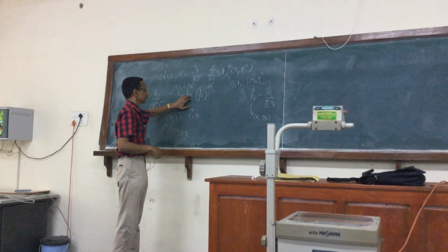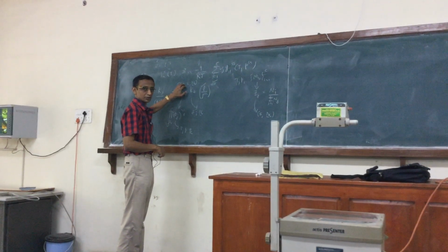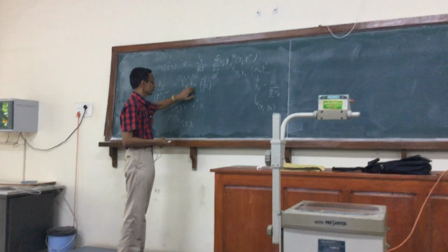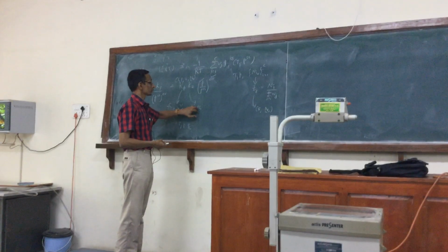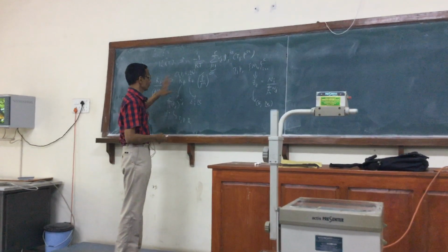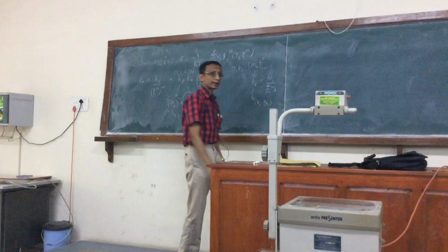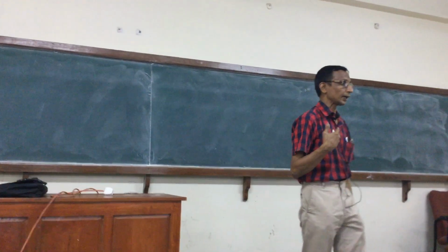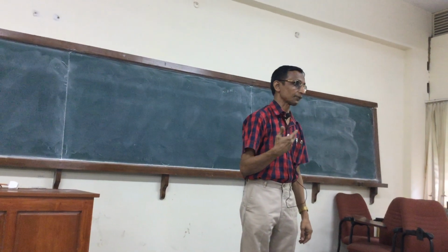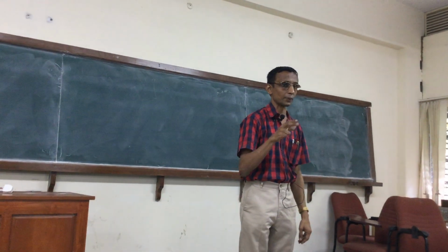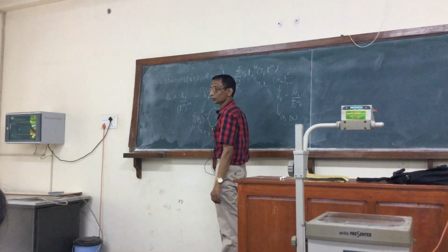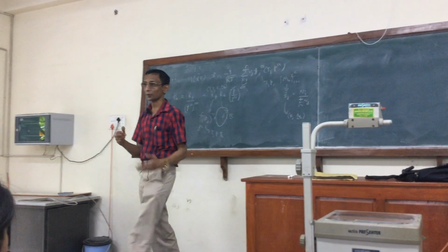So K phi times Kz, this is a function of temperature and pressure, which are usually specified, and the unknown extent of reaction. Kz is again a function of the unknown extent of reaction. Pressure is given. So everything is given. The only variable is the extent of reaction. That has to be equated to the value of Ka that I have calculated at the given temperature of the reaction from the tables and various other data. So this becomes a simple variable epsilon to be determined from the single equation.